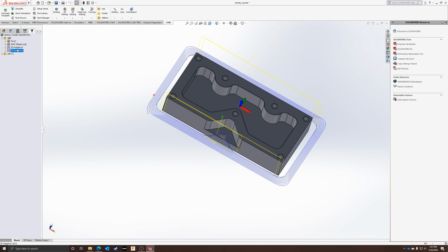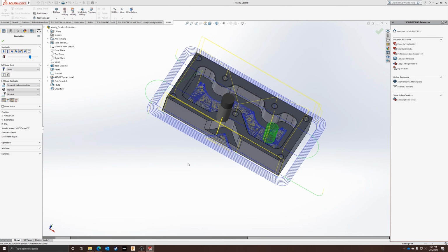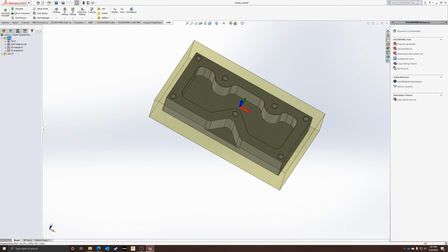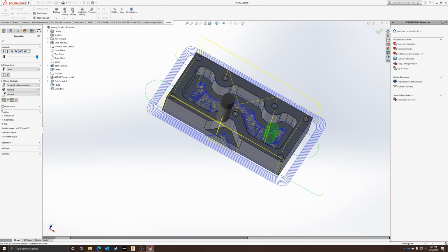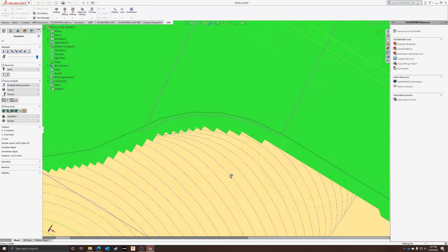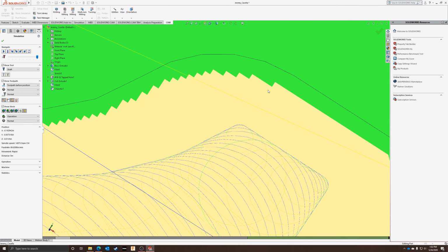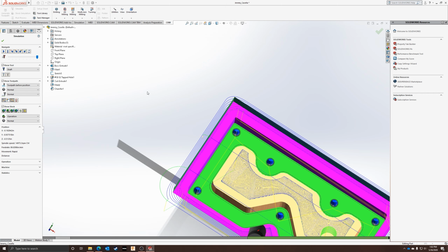Now we have our toolpaths. And then if I simulate this entire operation, right, we're going to look and we're going to see, whoa, oopsie daisy. There we go. There's going to be a nice even amount of material all the way through, right? It's fairly close to what's over here. It's all the same, right? And that's perfect. That's what we want. So now we're good. What's the final thing we have to do, right?